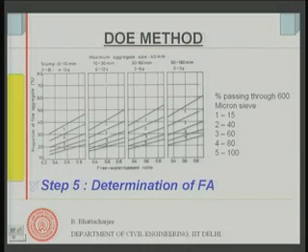In Indian standard, all these were actually calculated first for a specific water cement ratio depending upon your grade of concrete, and for specific compaction factor, specific zone of sand, and the shape of the aggregate, etc. And then we applied correction factors for each of them. Here, of course, fine aggregate content you determine straight away from these sorts of curves.